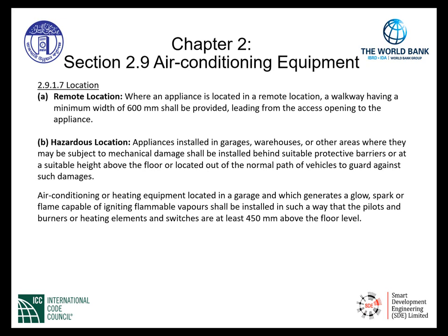B, hazardous location. Appliances installed in garages, warehouses, or other areas where they may be subject to mechanical damage shall be installed behind suitable protective barriers, or at a suitable height above the floor, or located out of the normal path of vehicles to guard against such damages.